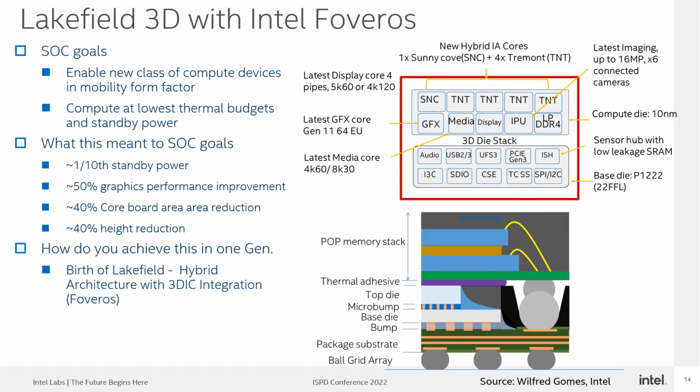Then let's talk about Lakefield, which was Intel's alternative for mobile parts. It was a small form factor solution for making everything smaller. So the SoC goals were to enable a new class of compute devices in a mobility form factor, and compute at the lowest thermal budget and standby power. Standby power was the key. So we had to target 1/10 of the standby power of usual. At the same time, 50% graphics performance improvement, 40% core board area reduction, and 40% height reduction for a